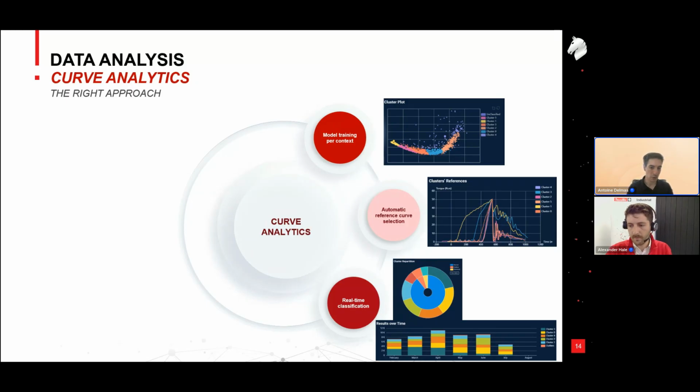This is actually some quality issues that we've detected at some customers. The over time one is a perfect example of that one I said earlier about temperature. If you see that one particular cluster is really common during the winter months and then goes away during the summer, it could be that your part is brittle in the cold weather or something like that. The cluster itself doesn't know that, but you can see if it's prevalent in cold months, maybe it's related to temperature.